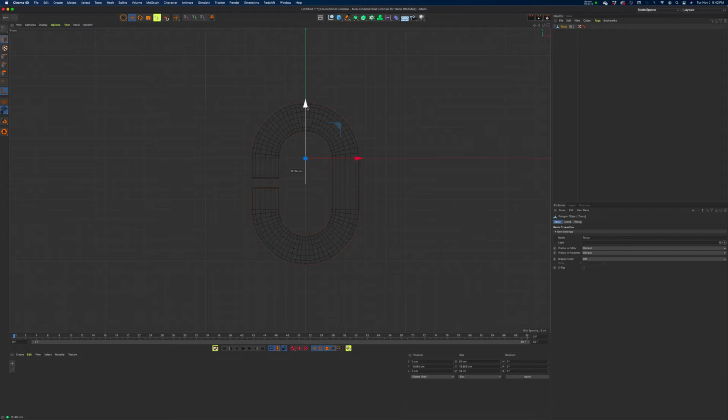peace of mind and just to make the point, what I did is while I'm in object mode, I turned on the axis tool, which allows me to move where the axis is. And I put it up here towards this center part, basically I put it right back at where it was at the origin, 0, 0, 0, and I hit apply there. And then I'm going to move out of that axis tool.